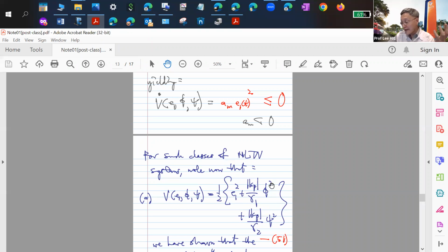You started off with some value for your control gain theta of T. If you don't know what to put, typically you might put 0. Or if you know what to put, you might think that it's somewhere near 1.5, you put 1.5. It doesn't matter. Whatever theta minus theta star is, it is also a number. So at 6:15 p.m. last week, the error is a number. Similarly, K minus K star at 6:15 when we started is a number. So at time T0, you can calculate the exact value of the ellipsoid. If you know all the quantities, that will be some number at 6:15 last week when we first started.